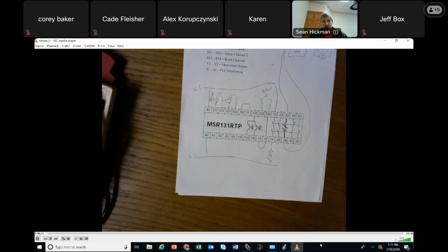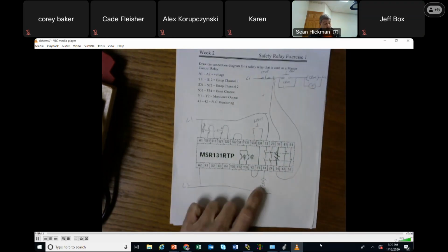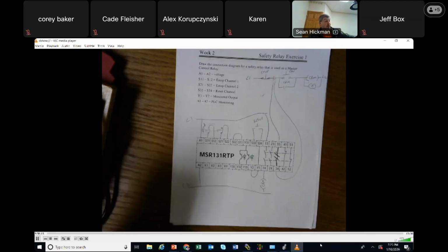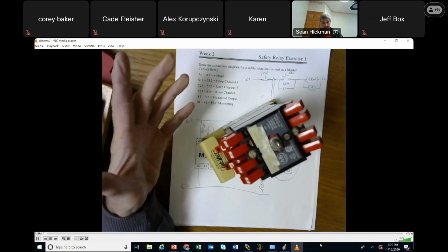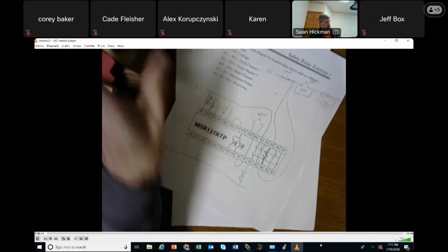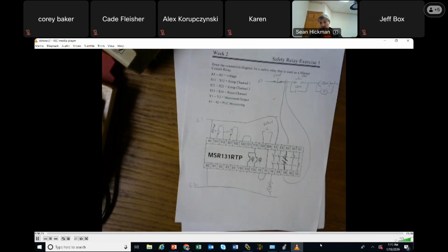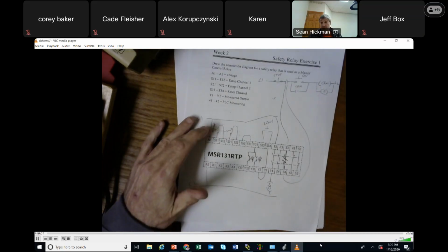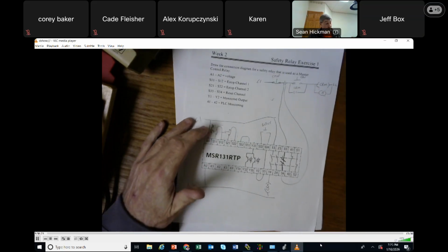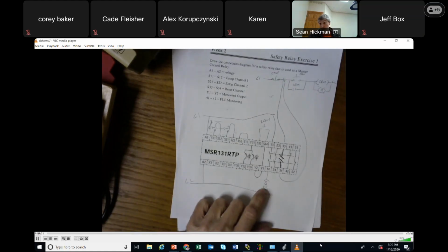And then just by turning on the safety relay, it would turn on this relay. The safety relay would turn on this one. Hitting the E-stop would open up those contacts and it would go off. Now, at this point, this only has an E-stop. The CRM doesn't have a stop.